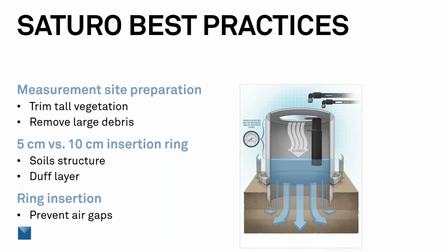And ultimately, you want to take care when you're inserting the ring. You're going to need some force to drive it down, but carefully make sure that the ring is going down straight and not moving side to side, because this will also prevent air gaps.